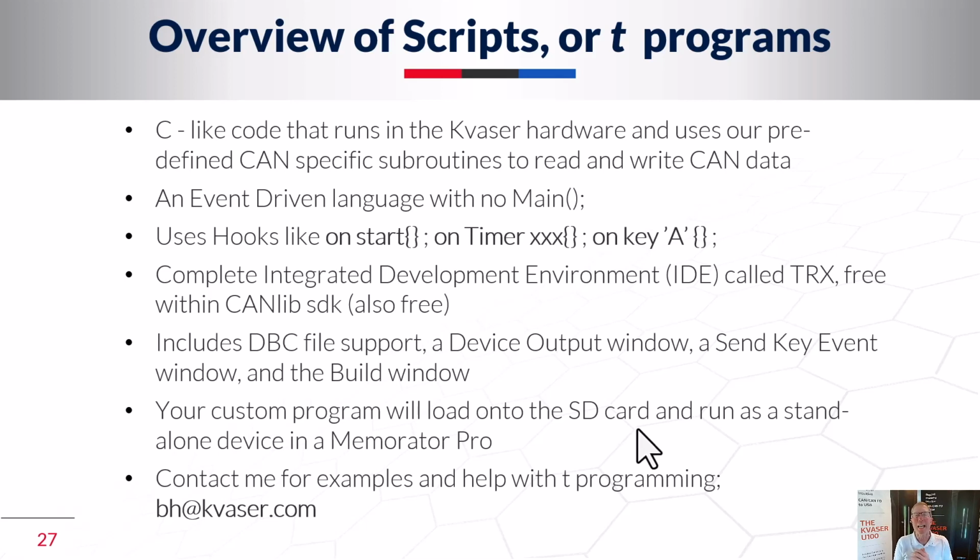So any particular presentation with a Pro device, in my eyes, isn't complete without at least a mention of T programming. T programming is our scripting language, and it's a C-like language. It's an event-driven language with no real main routine. It's got what we call hooks: on start, on timer, on key hooks. On CAN message is a really commonly used hook, and then it executes code on those particular events or hooks.